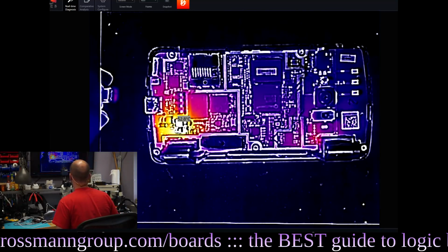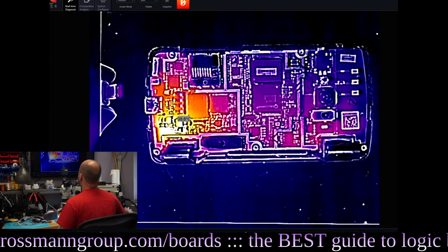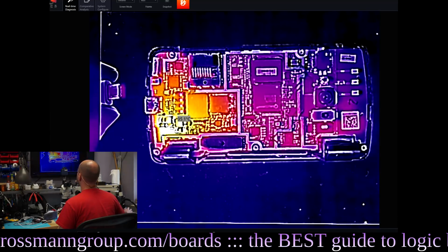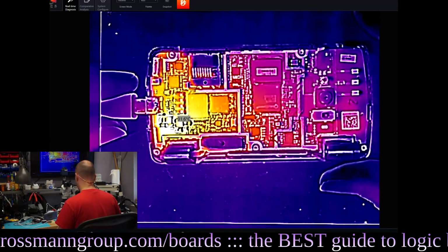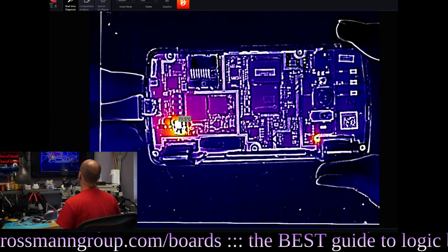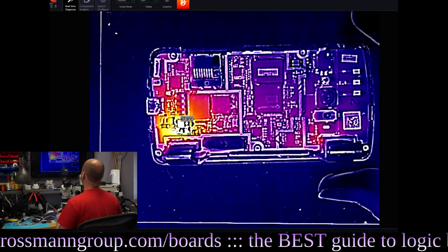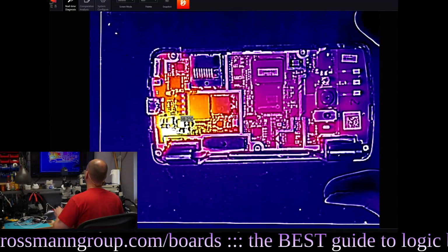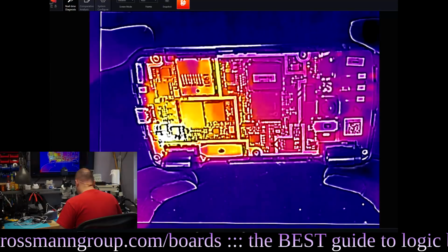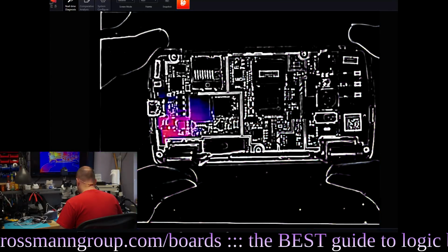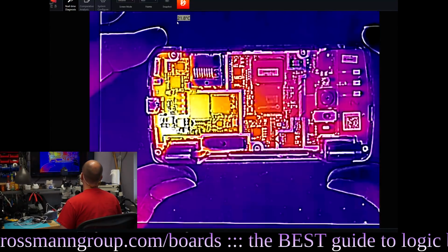90C. It's covered over here. I can't see it. That's 90C on that. Put your mouse pointer over it and plug it in. So there's a piece there that goes up to 80 Celsius. I have 130. How does that 130 Celsius? Yeah. So that MOSFET is definitely bad, and something up here in this corner is bad as well.